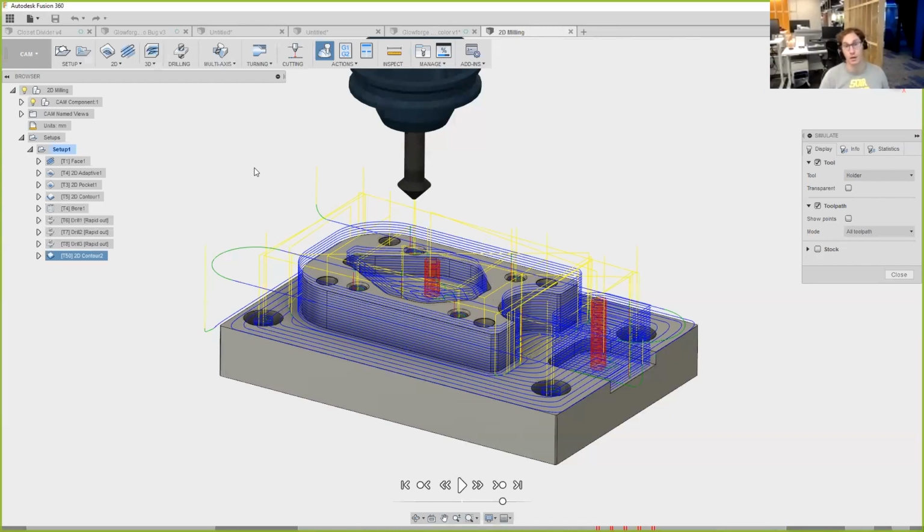So for example, Epilog Laser, they use a printer driver, and so from Inkscape or from Corel or from Illustrator, I literally would say file, print, and it sends the file straight to our laser cutter. In Fusion 360, in Glowforge, it works a little different. Glowforge wants you to use their web app, or web interface, to actually be able to load all your SVGs and control the intensity of the laser, like what the power is, what the speed is, the order of operations, all of that stuff is controlled on the Glowforge end. So trying to control it here in Fusion is a little overkill, but it can be done. So I'm going to show you how to do it anyway.